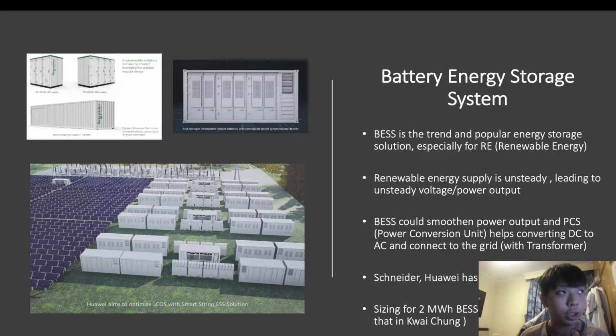To use for energy storage for peak shaving, or use for frequency response, or energy storage for collecting these kind of renewable energy. But most importantly, renewable energy supply is unsteady, as we know, affected by the temperature or the environment, the sun or the weather, leading to unsteady voltage or power output. The BESS could store this energy first, and smoothen the power output, and the PCS,